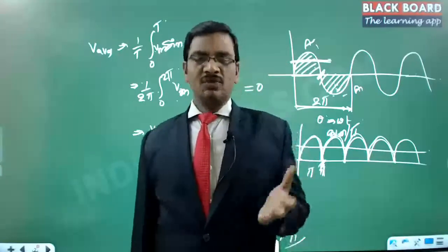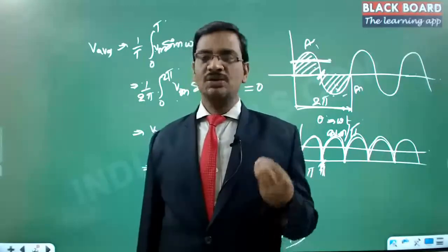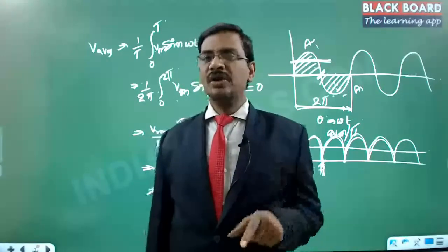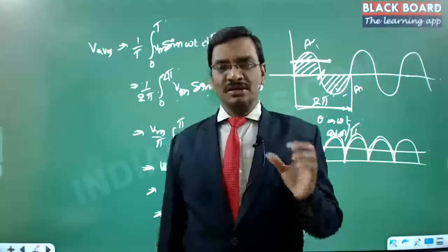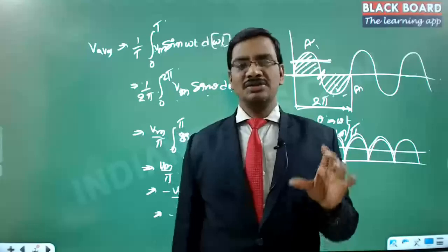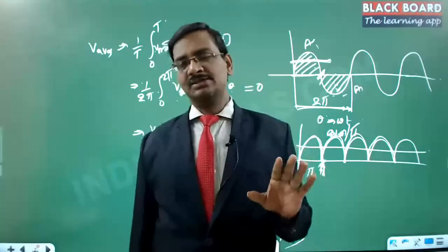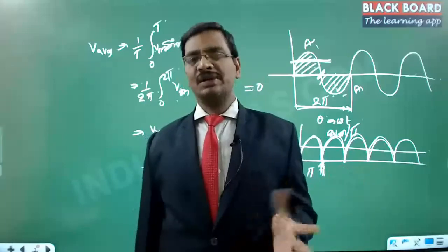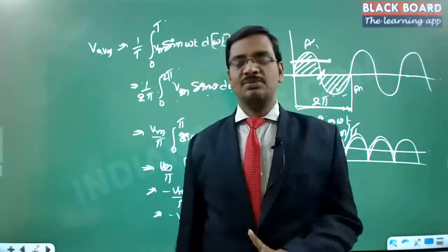There, the transistors, MOSFETs, everything is designed only to work for DC. So you want to identify what is the equivalent DC value coming out at the terminals. That is the reason the average value is meant only for DC calculations, not for AC calculations. We don't talk about the average value at all. It is just not required. Got it? But we always talk about the RMS value.